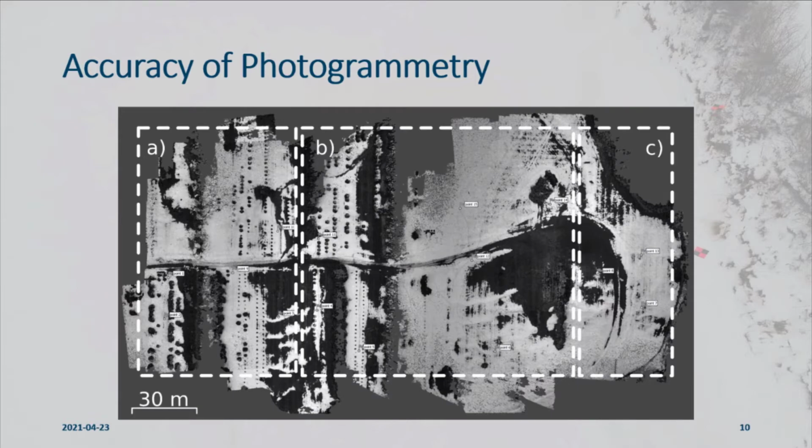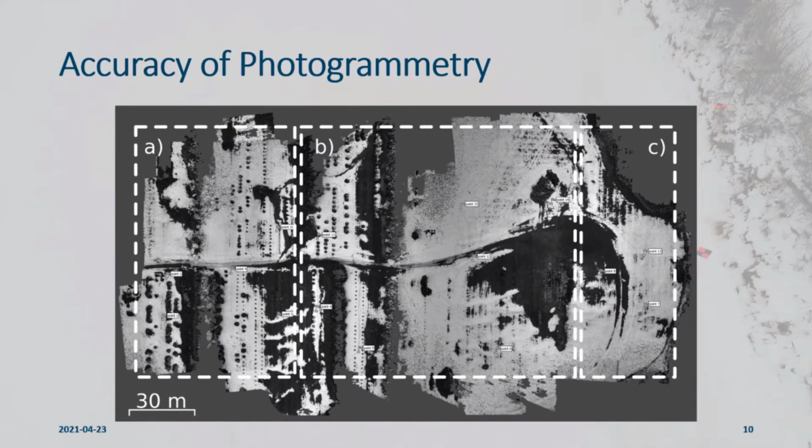So with all these limitations, we wanted to know if there was some kind of error that would be incurred, especially on the far side of the study area, which would be 200 or more meters away from our nearest known georectification target. So we set up a simple test where we flew the drone over a totally dry land scenario. It was a tree farm close to Winnipeg. We put out georectification targets throughout the area and then ran the photogrammetry algorithm using various subsets of those points, and then compared those results to the case where we used all of the points altogether.